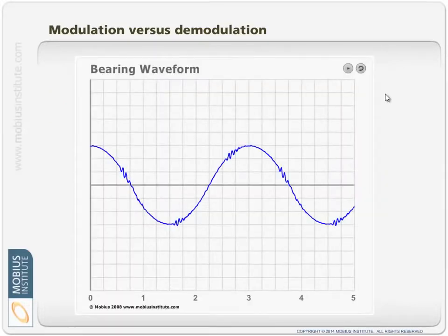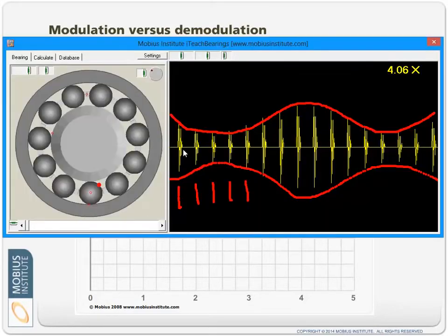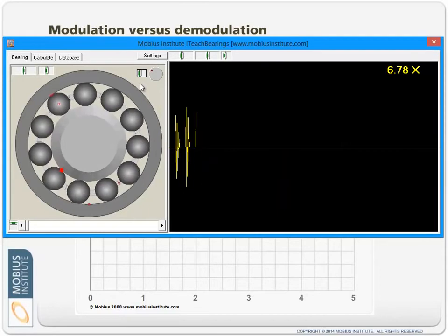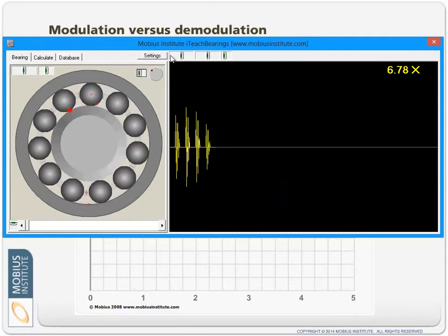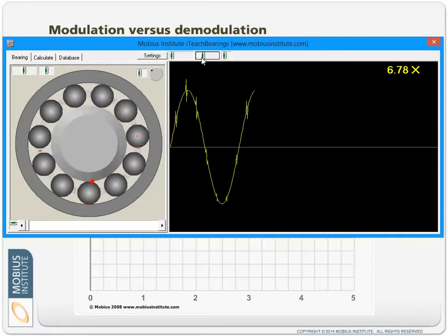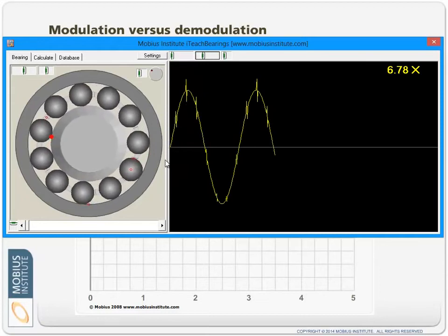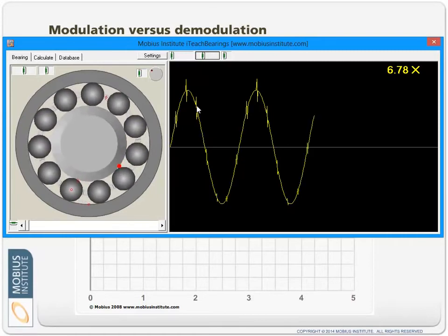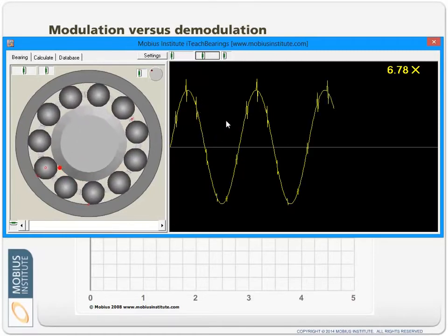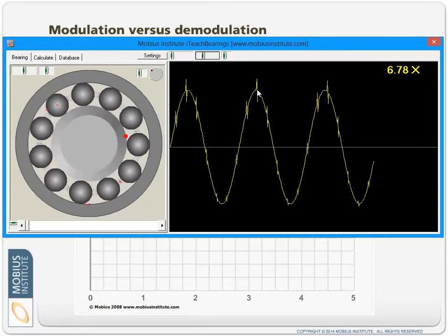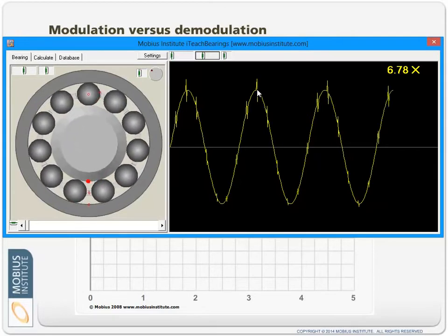And I could use the bearing simulator or this one. If I look at this vibration again, and let's make it that fault and this one. The situation is that in the early stages of a fault, we've got a little bit of vibration. Well, we've got the 1x vibration and 2x vibration, and superimposed on that is just a very little bit of vibration. Now, what I'm displaying here, the spikes are way too big than is the case in reality. So we have an early stage fault.